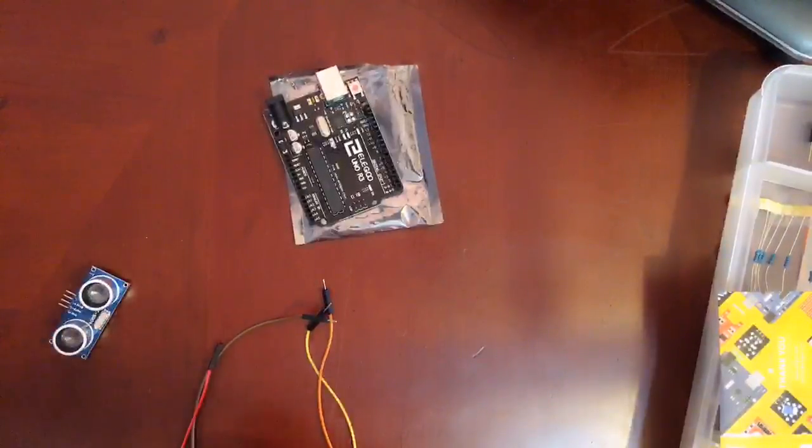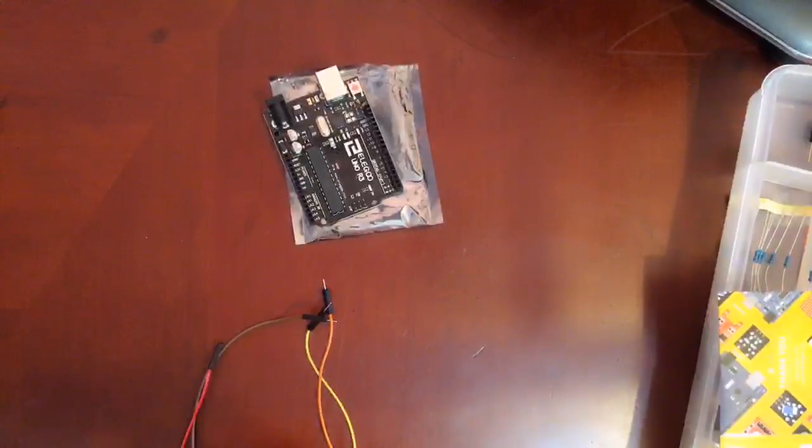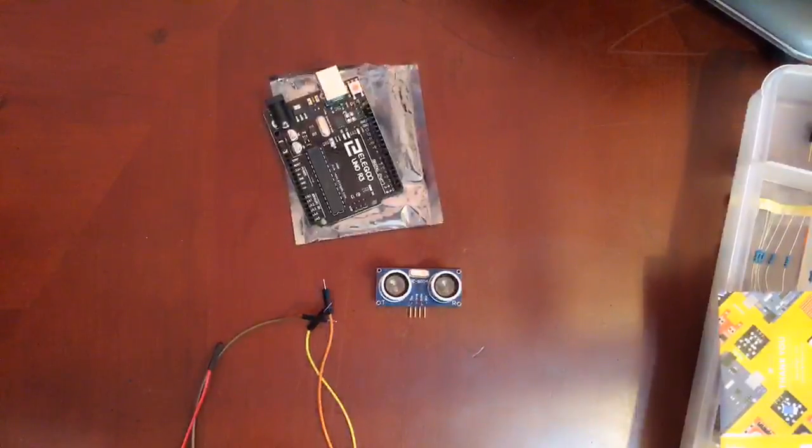If the signal comes back through high level, the time of high output I/O duration is the time from sending ultrasonic to returning. Test distance equals the high level time times velocity of sound, all that multiplied by 340 meters per second, then all of that divided by 2. The time diagram is shown below.